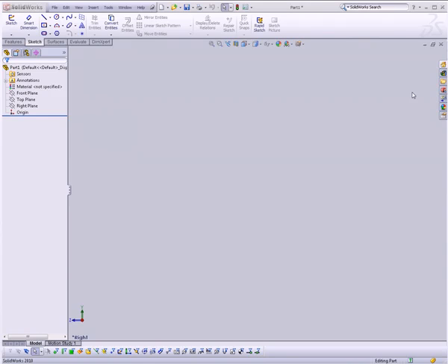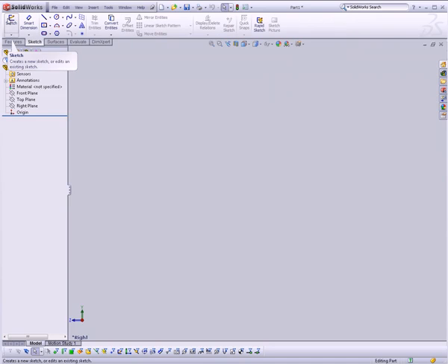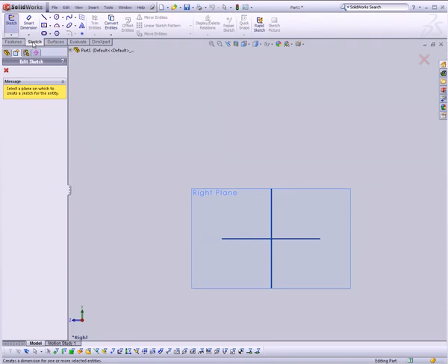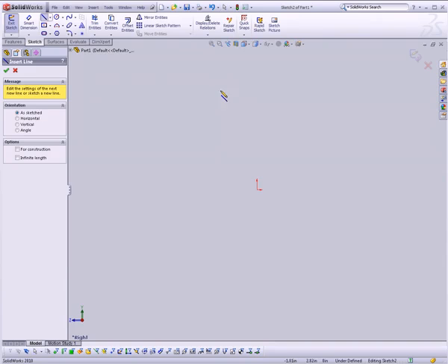So let's go ahead and start building our glass carafe, and we'll start with the revolved outer surface. Revolve is basically like you would expect. It's a surface that goes around a center. And we're going to need a two-dimensional sketch in order to create that. So let's start by clicking the Sketch button in the Sketch tab on the tool strip at the top. And then I'm going to click on the right plane in the viewport and choose my Line tool.